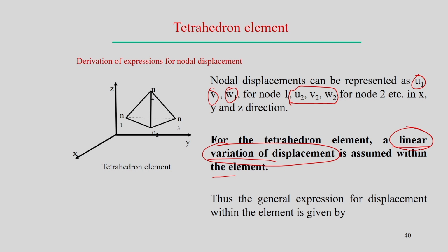So, it is not necessary to define some kind of node point in between. For example, between node 1 and 2, the displacement field can be considered as linear. So, considering node 1 and node 2 is maybe sufficient, but if we assume a quadratic variation of the displacement field, then it is necessary to define another node point in between 1 and 2. So, that is the difference.